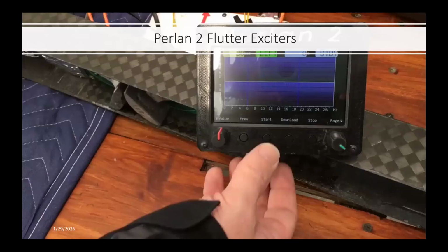And then the top graph is a bending measurement, how much it's bending, and the bottom graph on that little chart is the twisting within it. They had similar displays inside both cockpits. This is one that's sitting on a bench, obviously. They had similar displays inside the cockpits so that when they did it in flight, both pilots could observe the data. And just in case, they also telemetered the data down while they were flying.